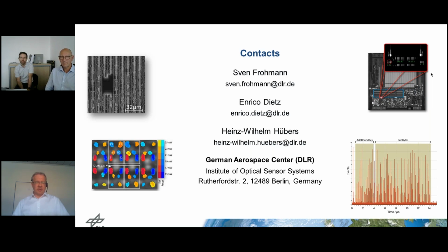Well, first it depends also on the kind of semiconductor. If you have gallium nitride, for instance, for power electronics, the maximum of the photo emission is in the visible range around 700 nanometers. But here in the silicon-based ones, the maximum is always in the near infrared towards the infrared. But so far, the problem is if it shifts more to the infrared, it's really getting difficult to measure it.